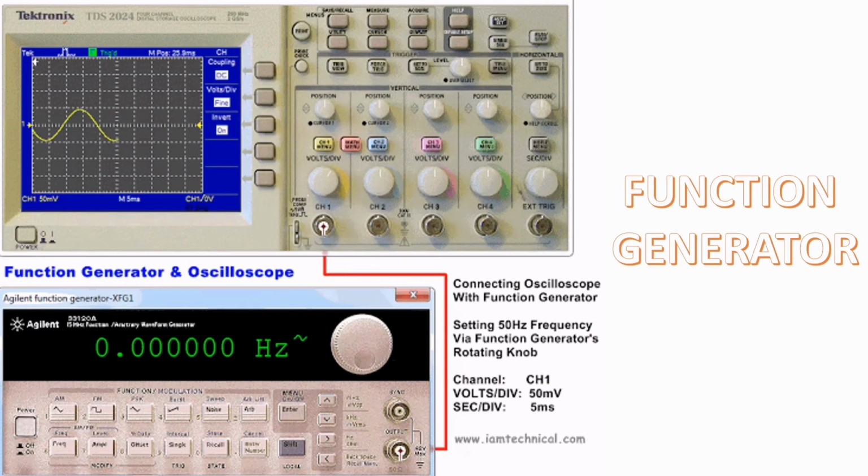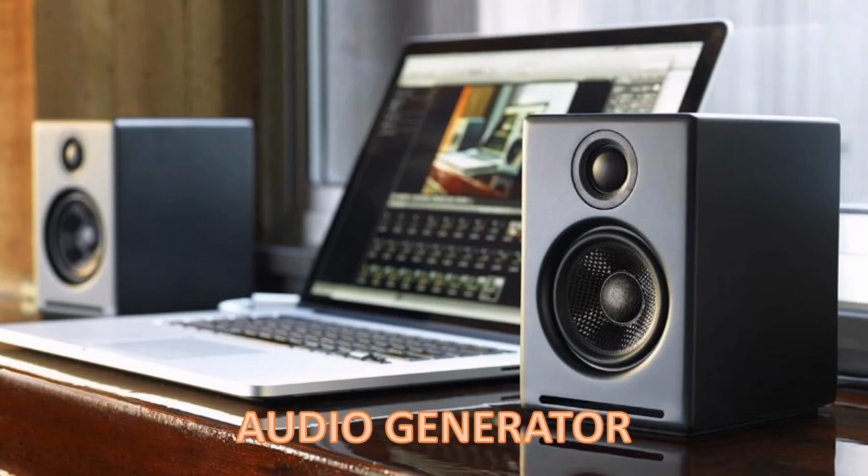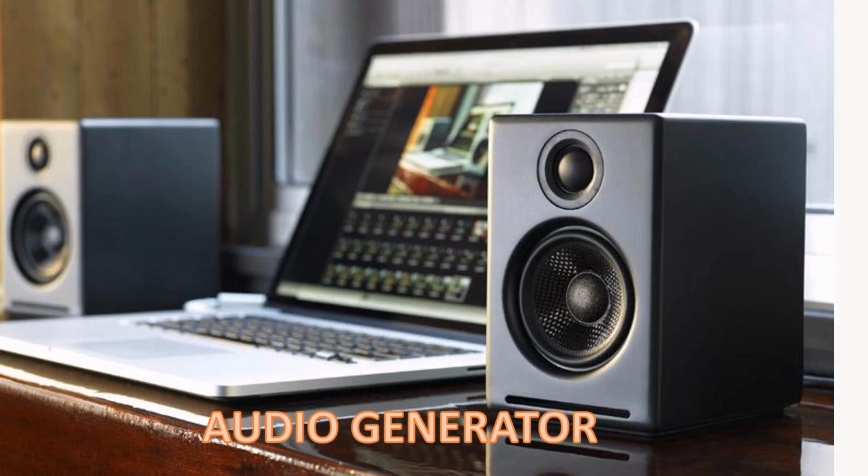It is a piece of electronic test equipment used to generate different types of electrical waveforms. Some of the most common waveforms produced by the function generator are sine wave, square wave, triangular wave, and sawtooth wave. The next example is the signal audio generator. Signal audio generators run over the audio range, typically from 20 Hz to 20 kHz and more, and are often used as sine wave generators.